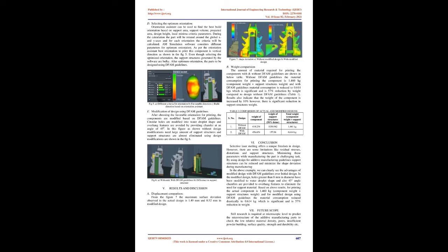Machine. Selective laser melting, SLM, is one of the additive manufacturing processes that works based on the principle of powder bed fusion. SLM is used for fabricating highly complex but low quantity products. The simulated component will be manufactured using SLM. Material. The material used in the SLM machine is Ti6Al4V, density 4.5 g/cm³, which is almost half the density of steel, and it is stronger than normal steel material, which is used in high-performance lightweight mechanical components for aerospace, dental and human prosthesis applications.